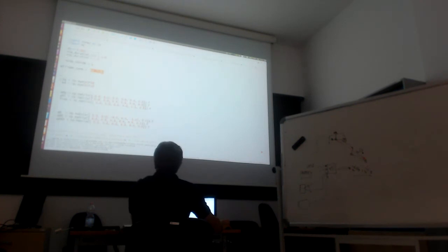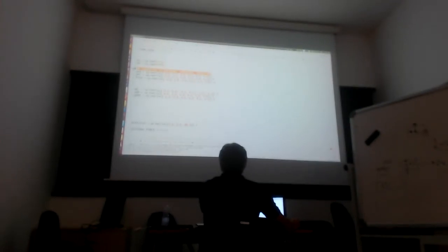And then you can set the proportional and derivative gains. These are the parameters for the reference sinusoidal trajectory: amplitude, frequency, phase shift, and the initial values. And then you can set the external force to true and add an external force of 50 Newton in the z direction.